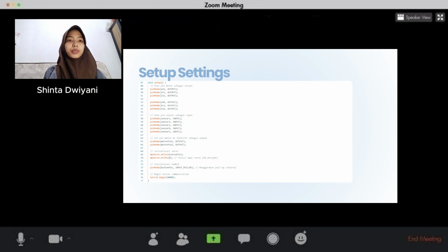Okay, I want to present about void setup. Explanation of the void setup function. Number 1, hardware initialization. Inside setup, you can configure analog or digital pins, initialize serial communication, start sensors, or configure other hardware that will be used during program execution.